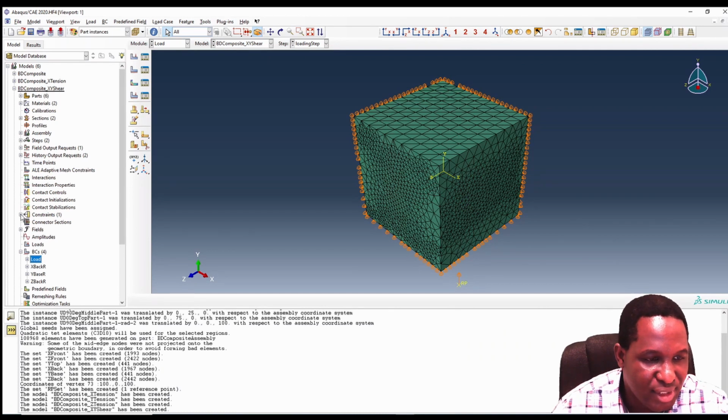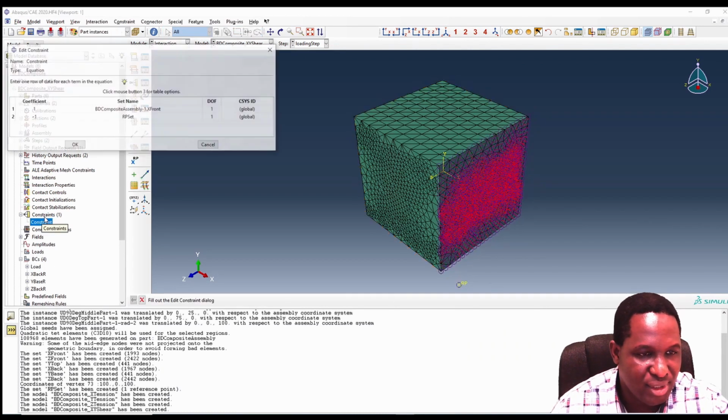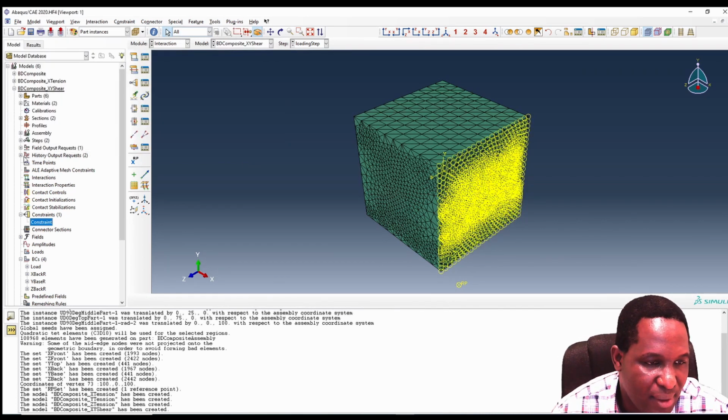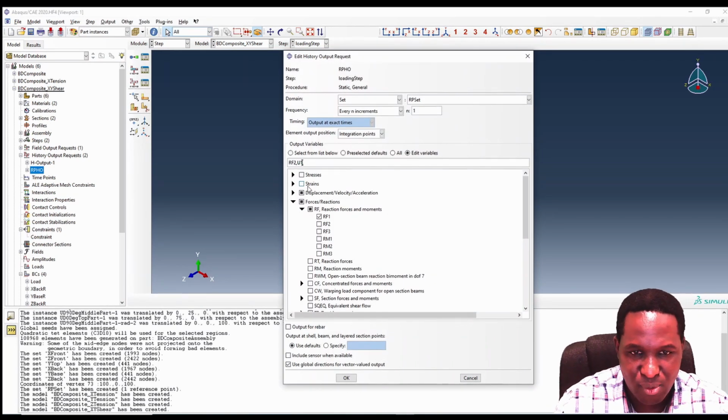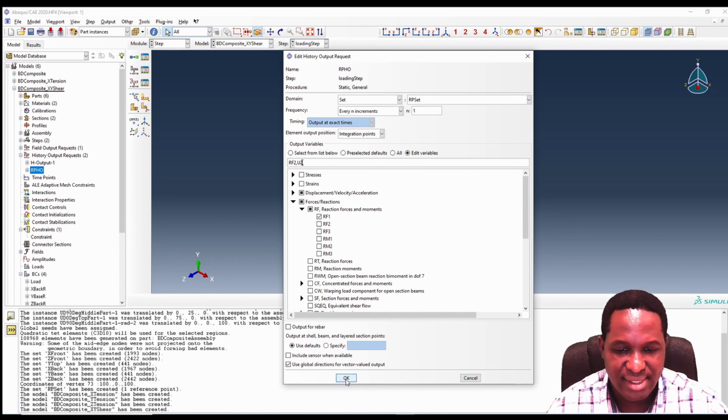And that's where the constraint equation comes in. So we'll double click on the constraint equation. The one direction, x front, is okay, but it's moving in the two direction. Now we could also go back to the history output for this shear case. Because we are moving in the two directions, this is no more one axis, it will be a two axis case.